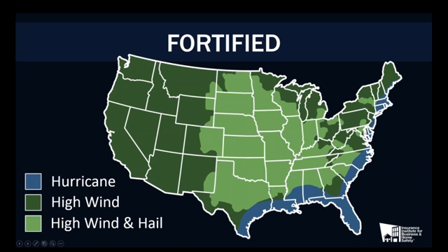If you think about extending this into Canada, this would be right along your Central Plains area as well, in the center part of Canada. So really, those are the areas that commonly experience the larger and more frequent hailstorms. Those are the areas that we really want to focus people on considering the application of an impact-resistant roof. It definitely gives more protection than a basic product. Again, we're trying to understand what the long-term performance of those products is and how the laboratory testing relates to the actual real-world performance, but it definitely is the best practice that's available at this point in time.